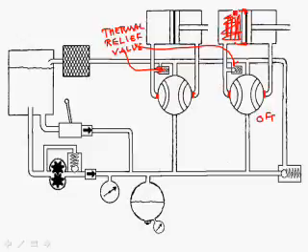It's going to get higher and higher, and the pressure is going to go much higher than the 3,000 psi or whatever it's set for. So it's going to start blowing things. It's going to cause leaks. Connections are going to pop. Fuel or hydraulic fluid is going to leak out.